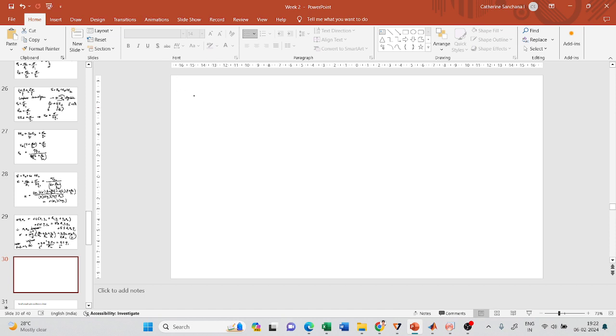Okay, so if you see a Maxwell model, is it a fluid model or a solid model? It is a fluid model. Why do I say so? It has a dashpot hanging separately, which means when I remove the stress, it is going to have a residual strain because of this dashpot.